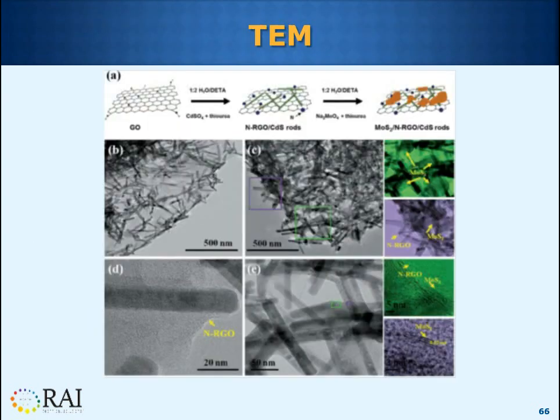As an example, here are TEM images of molybdenum compounds. Photo D in the bottom left clearly shows rod-like structures about 10 nanometers in diameter. This image gives an idea of the level of detail that is possible using TEM. I use TEM in cases where I need extreme details of the material structure, perhaps failure analysis of an automotive axle that broke and caused an accident. It helps me determine why the axle broke.